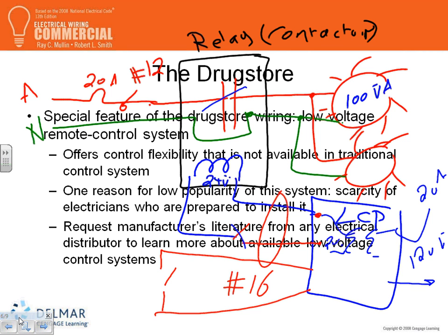So I can turn the switch here, control the coil that's inside the panel to turn the light on and off, and at the same time inside the panel, you can override the signal that's coming from this switch. Long story short, if the switch is off, you can override it by another contactor and turn it on and off. They use it for emergency light. If you need this piece of light, guys, as an emergency light, and it's a low voltage system, you can use it as emergency light.